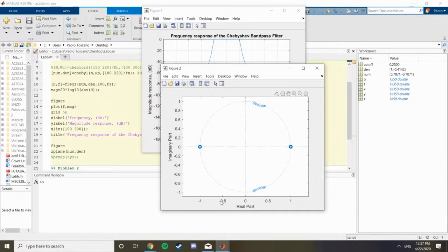And you have a bunch of poles very close to each other in a specific frequency band. On the unit circle, we start from z equals 1, omega equals 0, and we move forward up to omega equals pi. When we are close to a zero, our frequency response gets attenuated, and when we are close to poles, the frequency response there is going to have a peak.